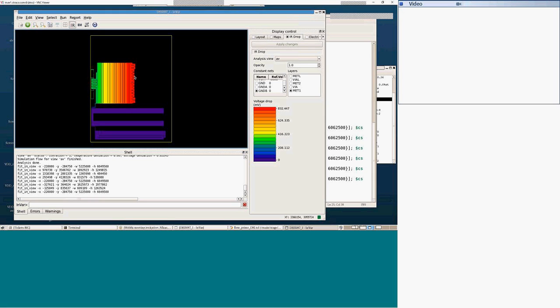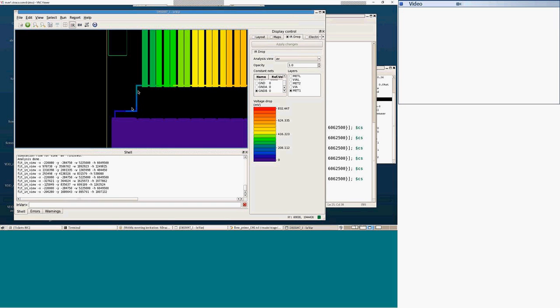But anyway, what I see, the whole area, this red-green area, is connected with the voltage sources to this very narrow segment. So the area is the dummy metal one. You say this green red area is dummy metal? Yes. And we should not assign any current sources in this area. You just instructed me to create current consumption in this area.